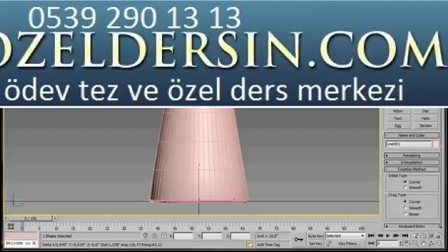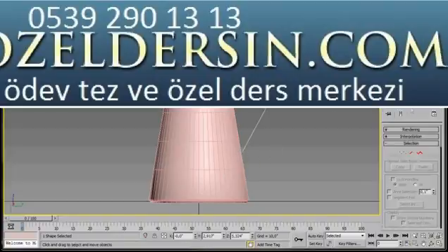Going to lower one a bit further down, and then the last one will be right down here, say 3/4 of the way down. Now let's go over to the Modify panel, and we're going to select the Vertex mode. We want a curved shape for the handle, so let's select the vertex, and from the flyout menu select Smooth. Now we can move the vertices around to find that nice curved angle we're looking for. That's fine. That's just the angle I was looking for. Let's go back over to the panel and click on Line to turn it off.